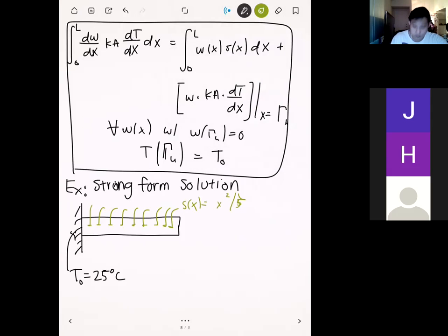And on the right-hand side, we're going to say that this surface here is adiabatic. All that basically means is that our heat flux is equal to 0 here. So when we plug into our equations, Q bar is equal to 0.